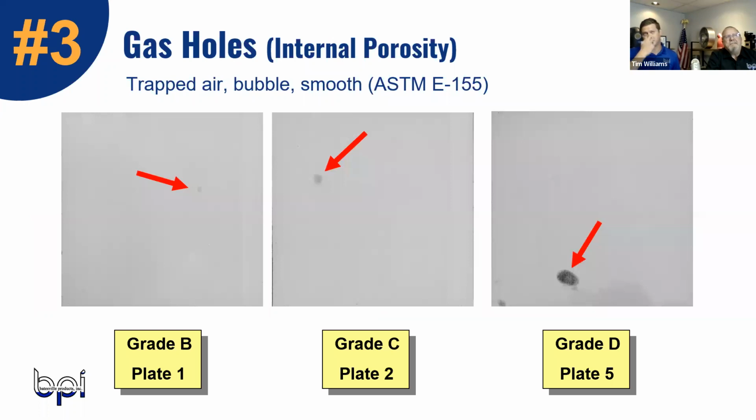So the next porosity that we are talking about here would be the gas hole porosity. So Ernie, explain to me what the difference is between the gas hole and the surface porosity, or the reaction porosity, we just talked about. Gas holes are almost always internal. They're almost always round in appearance, and usually they're very localized. They're usually based on metal turbulence, either something coming down the down sprue or something leaking in at some point in the gating system.